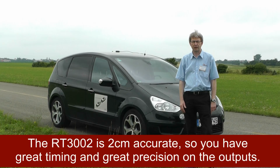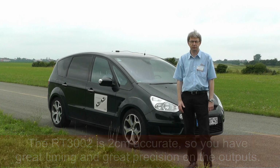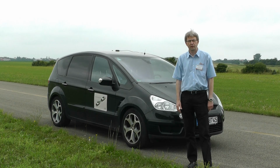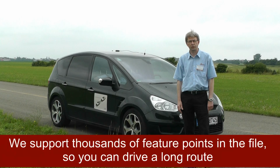In the feature points we have a track laid out here with a number of fixed points which are defined, and those fixed points are defined in a file which the user can specify, and then we can import that into the RT range, and the RT range will in real time calculate which are the nearest points within a defined field of view. The field of view is also configurable, so with the field of view we can define the minimum and maximum distance, and also the angles, both the angle of orientation and also the breadth of the field of view.